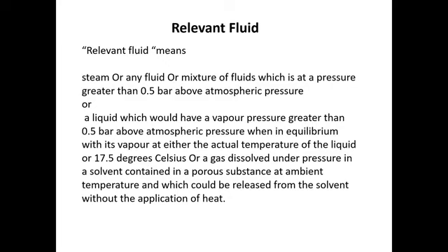Another definition of the relevant fluid is a liquid which would have a vapor pressure greater than 0.5 bar above atmospheric pressure when in equilibrium with its vapor at either the actual temperature of the liquid or 17.5 degrees Celsius, or a gas dissolved under pressure in a solvent contained in a porous substance at ambient temperature and which could be released from the solvent without the application of heat. So that is the pressure as well as the temperature conditions from which we can understand what exactly the relevant fluid is.